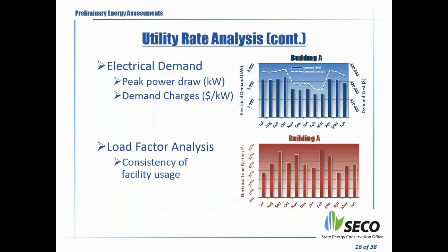Since we very much like to have the demand data, once we have it, we will present in the final report, for each month, how many kW you have used and what charges you have paid for it. Just for your information, for typical large facilities, anywhere from 30 to 45 to 50% of your electric bill may consist of demand charges.